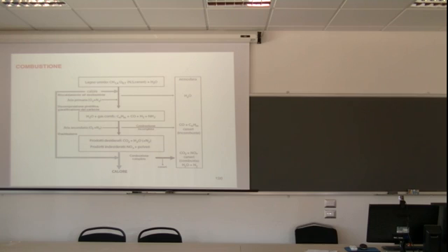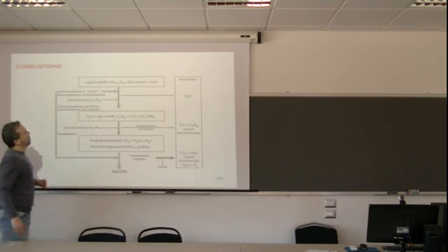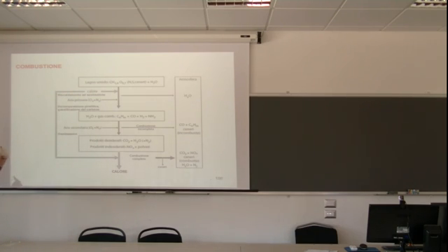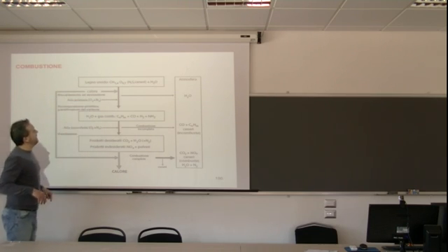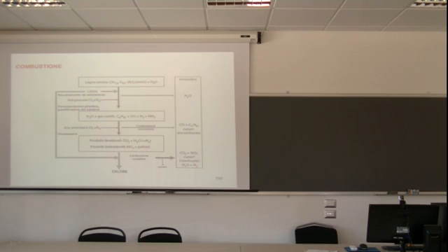Of course it's an average value, but for one carbon you have 1.4 hydrogen and 0.7 oxygen. This is an average value of the composition of biomass. So, as you can see, we have the first step when you have the heating and drying of biomass, and you can see that steam water goes into the atmosphere.